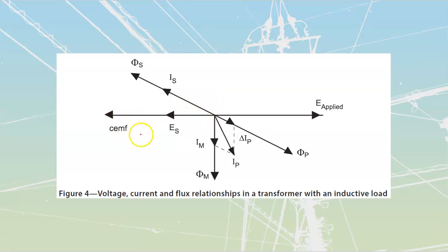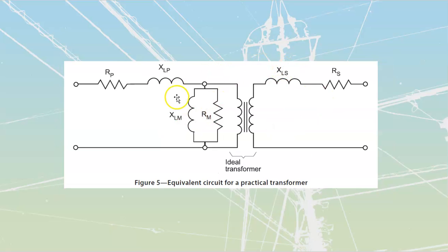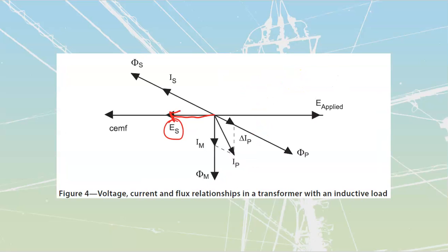So this is where my secondary value of voltage is over here. If I did not have the inductiveness of the transformer itself, what I should have would be a secondary current over there. But because we have got the transformer components itself, to show that in the next little bit over here, you know, these XLs that we're going to have, the leakage on here, as well as the actual inductance that we have on that coil, because of that, my current moves off of the voltage and lags it a little bit. It's not lagging it much, right?